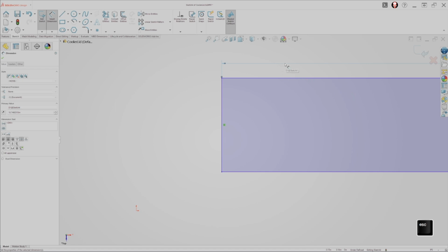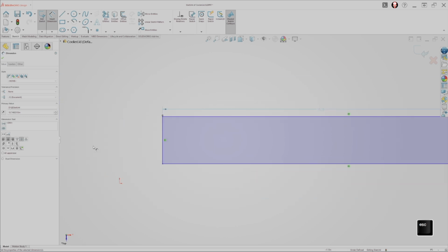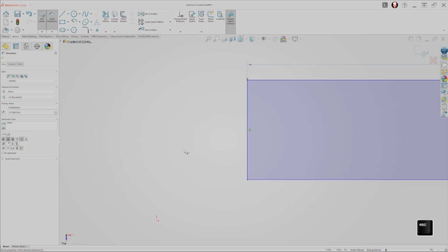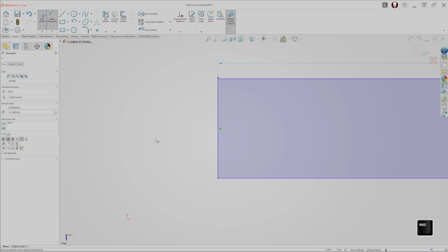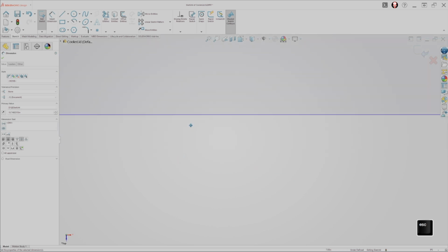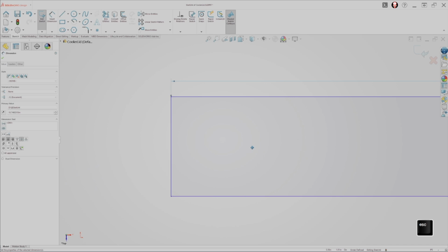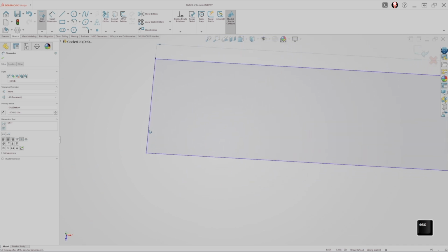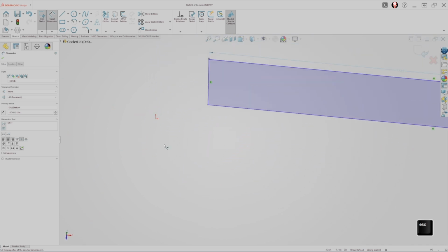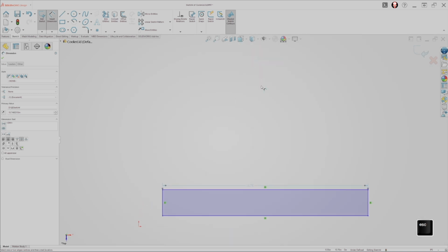Let's use this moment now to show how we can reorient ourselves in this view. Now, people don't always talk about this because it's like second nature, but let's just go into a little bit of detail here. If we hold the left control key and the middle mouse button, I can pan, or go left to right, up and down. So that is helpful when I'd like to look around a sketch. But in a sketch, you generally don't want to orbit the view like I'm doing on the screen right now. When we orbit into a third dimension, it's just more likely to create errors or to be confused.